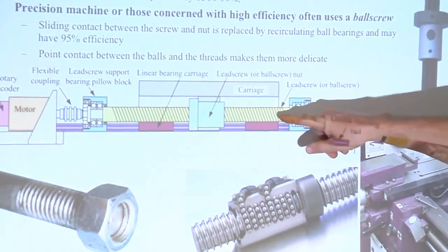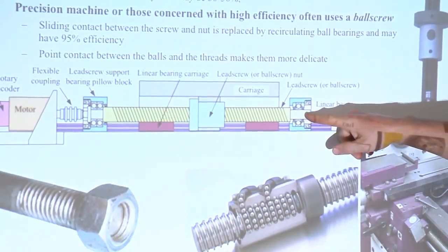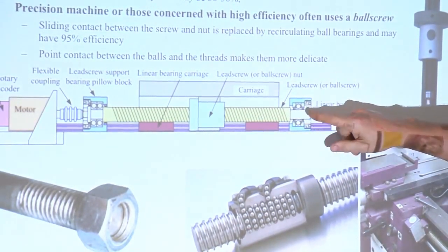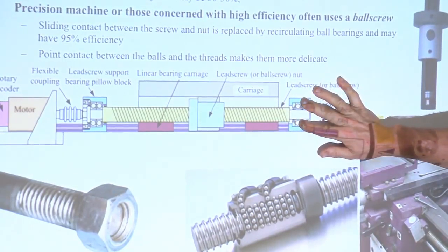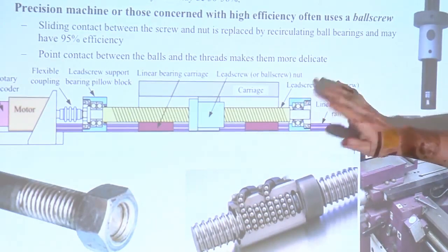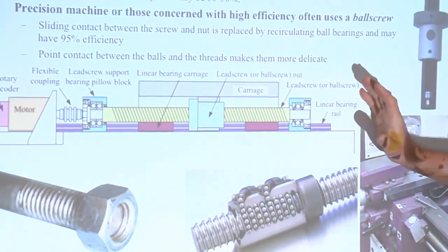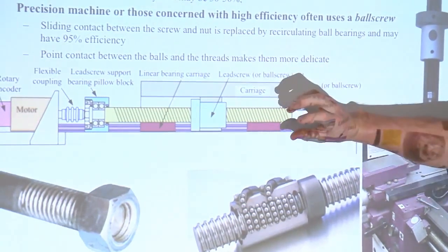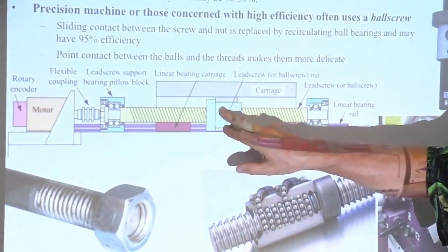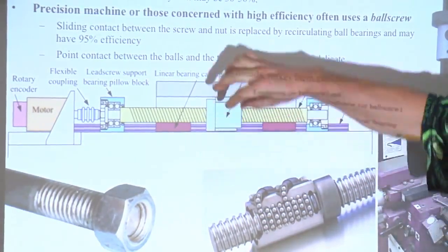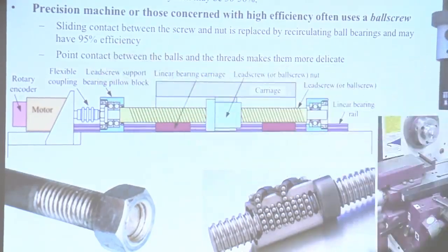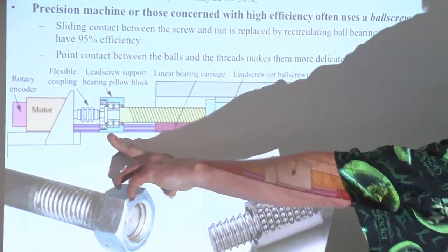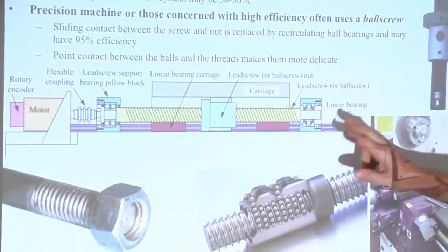The other end of the system, the lead screw or a ball screw shaft, goes through the bearing, and it's a sliding fit with the ball bearing unit here. So all the thrust of the screw that happens when you turn the screw and the nut is not allowed to turn, so the nut wants to move, and if something's restraining it, that's a force that then is transmitted through the screw to the bearings here, or taken up at this one end. Why is it mounted this way?